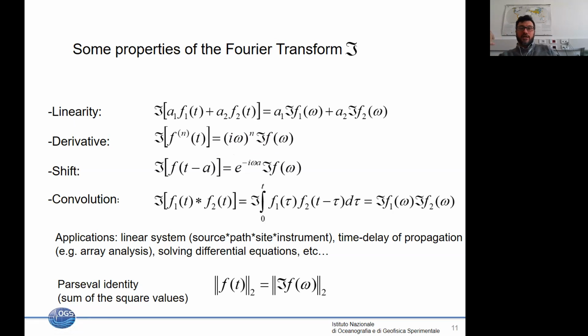If we apply the inverse FFT, we can go from the frequency domain to the time domain and obtain our time series. This is just one way, but very often in engineering, we have the contrary problem. So we record acceleration but we want to calculate velocity, or even more, in the last years, the displacement. And this is done following the inverse procedure.